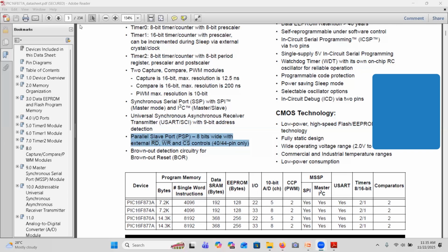In that, the architect, by understanding the customer requirement, will look at it technically. The customer will say, I have two modules, they have to exchange information. If this information comes, this module should do this. Like that only the customer will say. He won't say you use CAN, you use I2C, you use SCI. No. He will say, I want to see the album status or street name in a display, ACC status in a display. So the customer requirement will be more generic. He won't ask you to implement it in CAN, FlexRay or LIN like that.